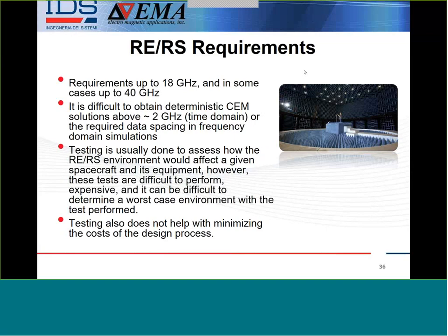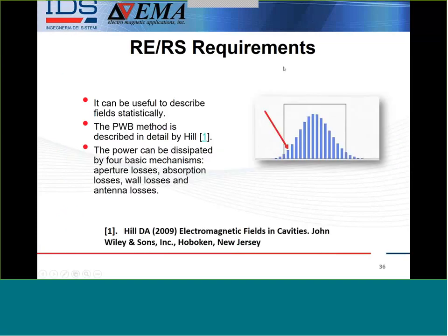It's not acceptable for EMI EMC. So how do we design it before we know? And the trick here is don't try to brute force it. Don't kill yourself. Approach the problem in a smarter way. Let's use statistics. So everybody knows about reverb chambers and using statistical electromagnetics for testing, and the revolution that that's done for being able to assess multiple frequencies and multiple incident angles at one time in a reverb chamber.